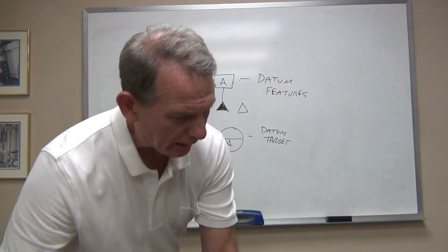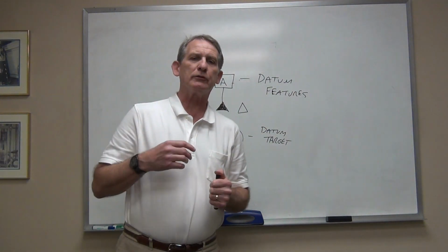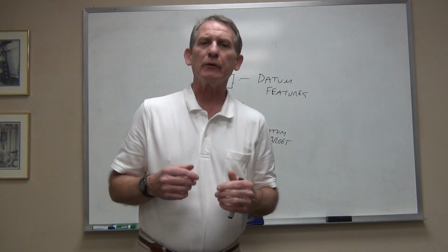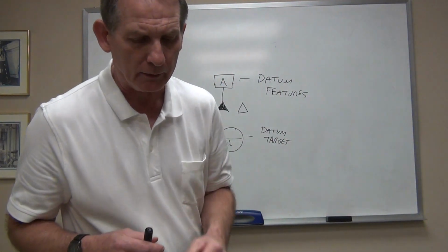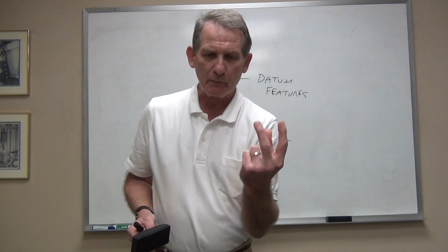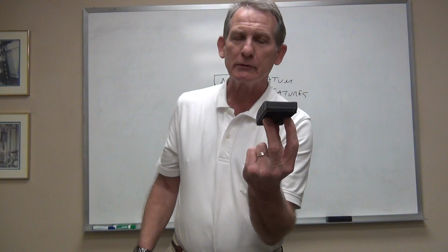The upper area is often empty, but there are instances where we have to specify what the nature of the contact is on that datum target. In the case of my 3 fingertip points, I'm touching on 3 geometric points.